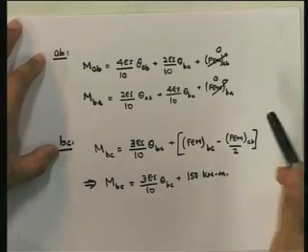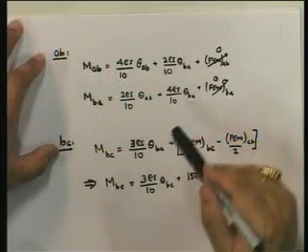MCB we know is equal to 0, and theta CB we don't need to know because we have condensed out theta CB. Remember that theta CB is not equal to 0. In the modified fixed hinge, theta CB is not equal to 0. However, we consider the fact that MCB is equal to 0, and so theta CB can be statically condensed out, and we are only left with theta BC. Theta CB is not an essential deformation quantity required to define the force member relationship in BC.